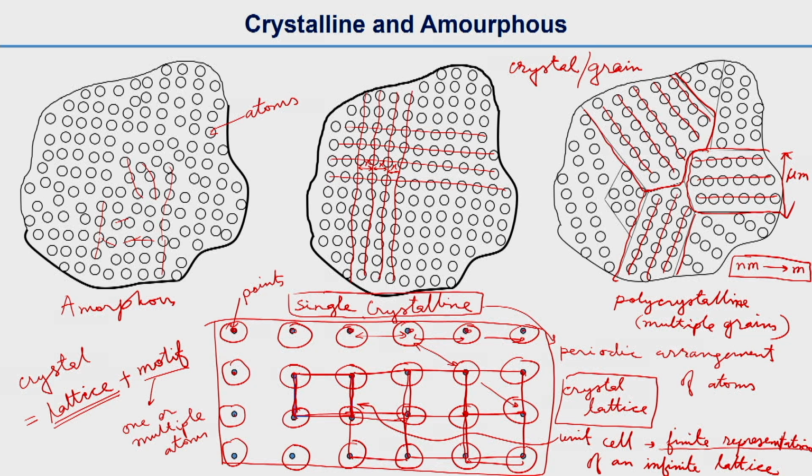Now one important thing to mention here is that for a metallic, crystalline material, the single crystal is anisotropic. As you know the definition of anisotropy, it means the material properties are different in different directions, and for a polycrystalline material generally we consider it isotropic.